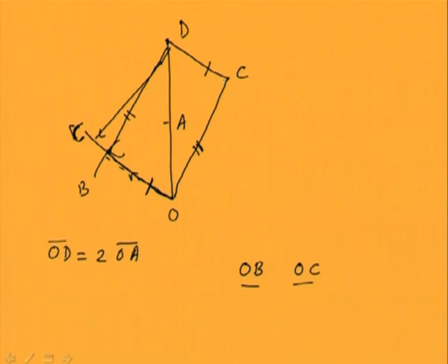Now because it is a parallelogram, you can see that this particular line here, AB is equal to AC. That is the condition we require, because this AB is the effect of the trial unbalance and it should be equal to AC, and they are in opposite directions, so negative.